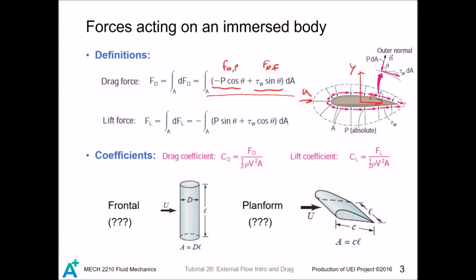The two fluid force components are compared to the stagnation pressure as if the flow is frictionless. To see this, we apply the Bernoulli equation between a point far away from the surface and a point on the surface. If the gravitational effect is negligible, we can write... so point 2 is of course the stagnation point, so this term goes away, and if the free stream pressure is atmospheric, it is now clear to us that the stagnation pressure is in the denominator here.